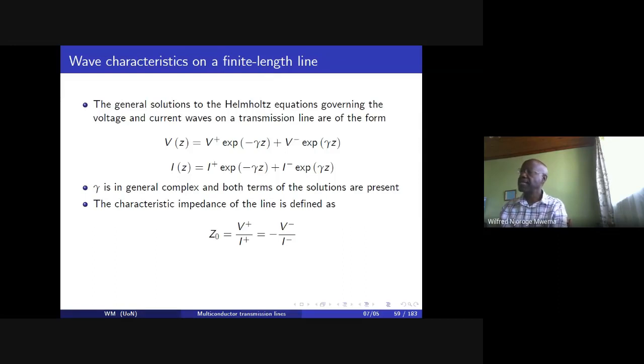But what we'll see is that the relationship between V(z) and I(z) is through a differential. That is, it's a derivative, so to speak. And therefore, if we differentiate the voltage waveform, we'll see that it will be related to the current in some given way.